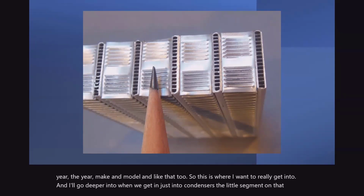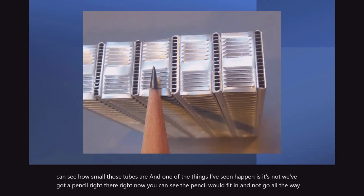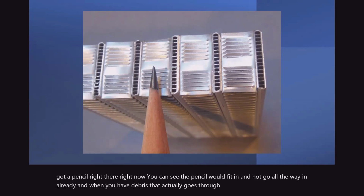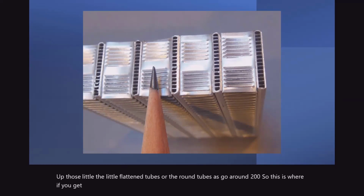But you can see how small those tubes are. One of the things I've seen happen, we've got a pencil right there, and you can see the pencil would fit in and not go all the way in already. When you have debris that goes through the system, it will start plugging those little channels up, those little flattened tubes or the round tubes. So if you get a compressor that explodes or you get a little bit of debris floating around inside of it, a lot of times you can't just flush the systems out.